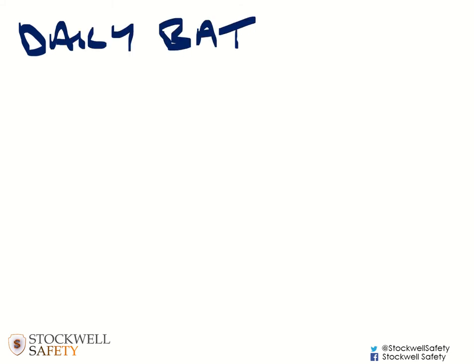In this video, I'm going to go through how to calculate the daily bathing load for a swimming pool, or the bather load. This is the maximum number of people that should use the pool over the course of a day. So whatever a day is for your type of pool. Not many pools are open 24 hours a day, so it'll be from the time you open up in the morning until the time you close down in the evening.